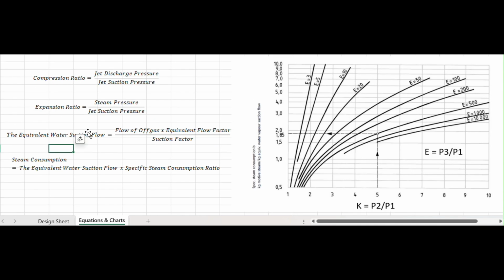Now, the suction factor, that would basically use the steam temperature. In our case, it's like 215, right, our steam temperature. So that would be somewhere here, okay? And then the line that you need is for your motive fluid molecular weight. So in ours it's steam, right? But you could use any. You could use air jets or nitrogen jets.